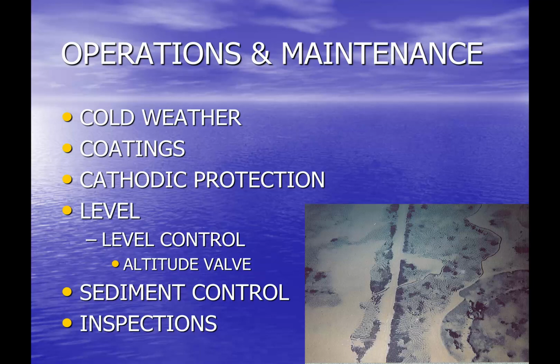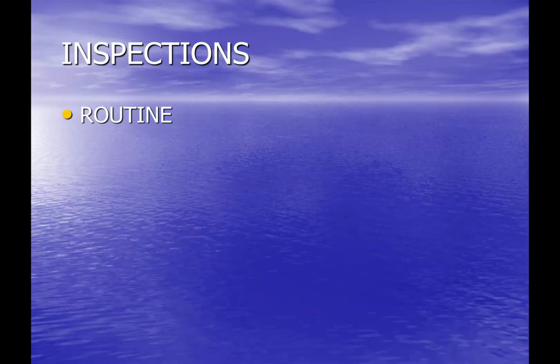And then ultimately, as with any important facility, we need to pay close attention to it. We need to inspect it and evaluate its ongoing condition and see problems before they become too big a deal. The inspections we'll talk about here come from recommendations from the American Water Works Association that have defined some different periods. The first one is what they call routine inspections, and these are typically going to be, from a time frequency, daily or weekly, depending on agencies and depending on resources.